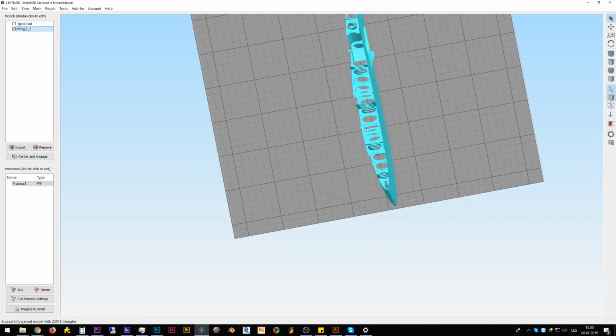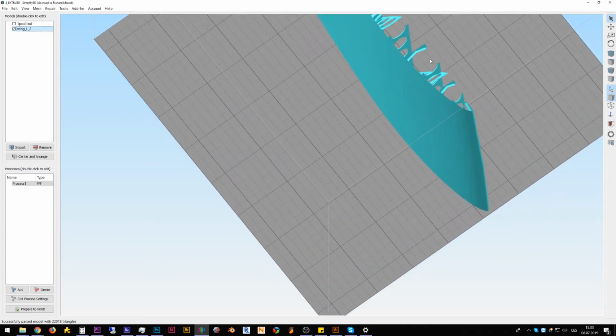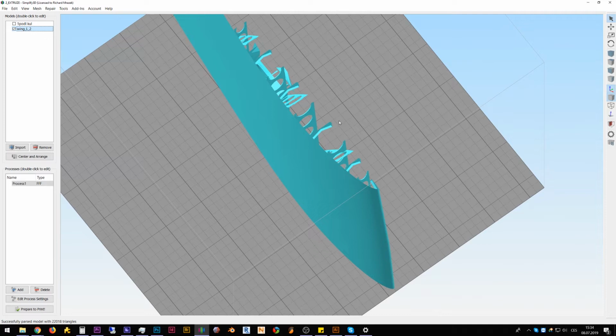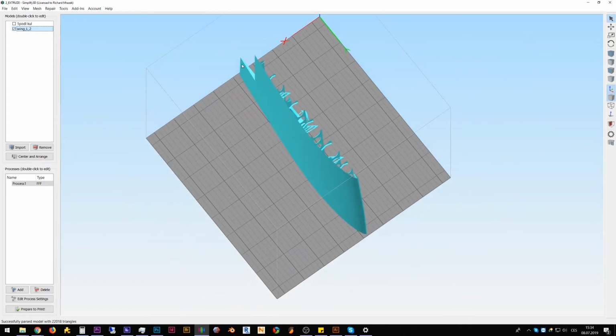This inner reinforcement is printed independently of the outer surface, because we need to print the outer surface without stopping, and after that we want to print the inner reinforcement which will be connected with the outer surface. But this movement of the nozzle must be continuous.